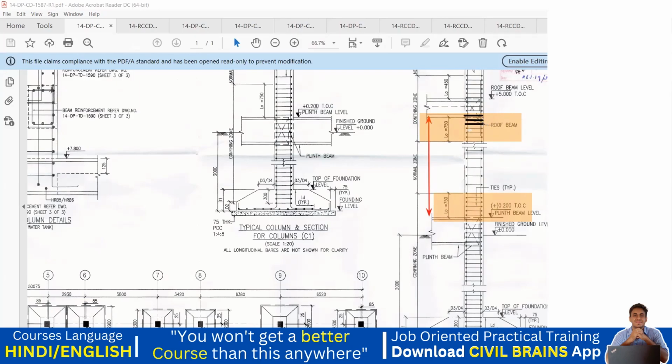Since we are putting the structure in an earthquake resistant zone, we want to make the zones ductile. I mean zones wherever there is an interconnection, because this is a slab and this is a beam ending. So this zone I want to make more ductile. More ductility I can give by providing more reinforcement at closer spacing. Similarly here also I'm going to do closer spacing. Got it?